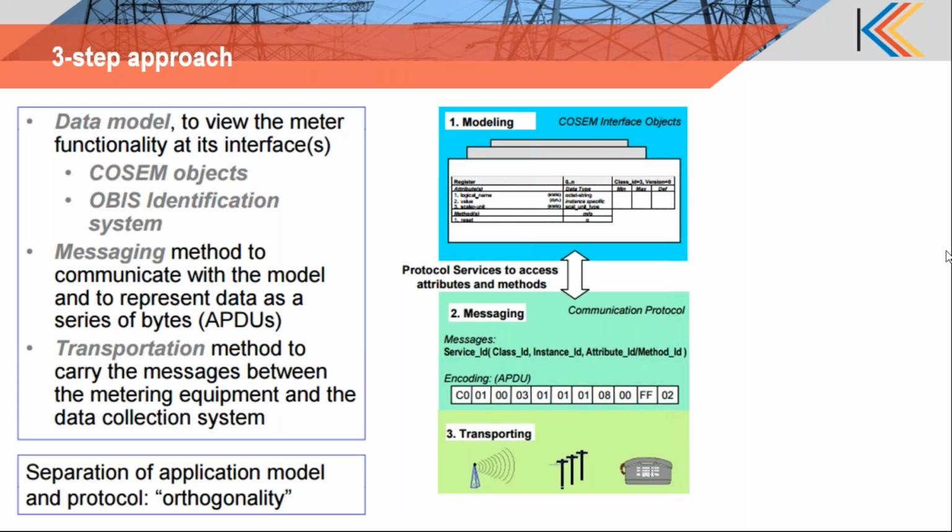No, the DLMS UA certificate is not sufficient for companion specification compliance because, as I said, the DLMS User Association does not really check the functionality. For example, even if somebody is making a residential single phase electricity meter with DLMS protocol and goes for DLMS User Association certification, without any relevant data like voltage, current, energy, power or load profiles, any of the typical data expected in a single phase meter, if none of this is present in a meter, they can still get a DLMS certificate.